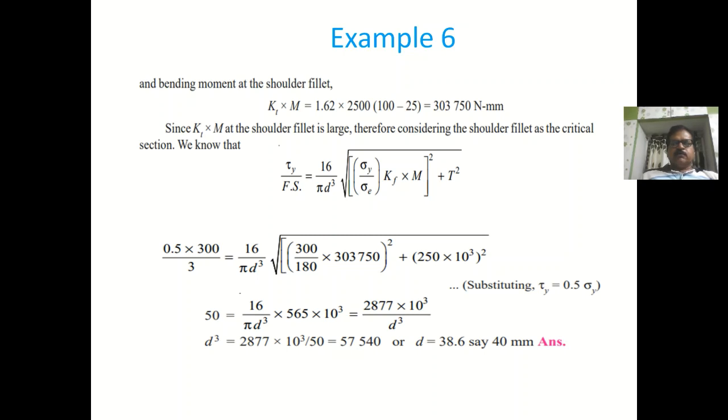And then for definite life and indefinite life we use various approaches. In definite life we use the SN curve, and with the help of the SN curve we find out the dimensions of the member, or for the given dimensions of the member we can find out the life. S stands for stress and N stands for number of cycles of operations.